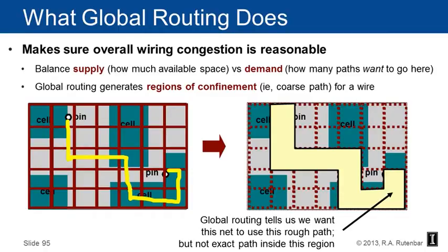So I route the wire in the G-box grid, and what it tells me after I've routed the wire is that when I am ready to embed the wire in detail, I should put the wire in the yellow box, the yellow serpentine path, the thing with the star in it. And you know what? That's going to be tremendously helpful to the efficiency of the router, because if I don't have to expand the route across the entire surface of the chip, if the region on which I run my detailed router is just the smaller yellow box, it's going to be dramatically faster.